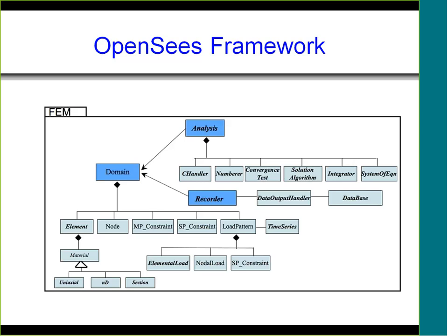Unlike some commercial applications like SAP or other software, if you don't specify the recorders inside of your file, you won't have any output after you finish your analysis. So to see the results of your analysis, you really need to define all recorders, or all recording objects, for your model.